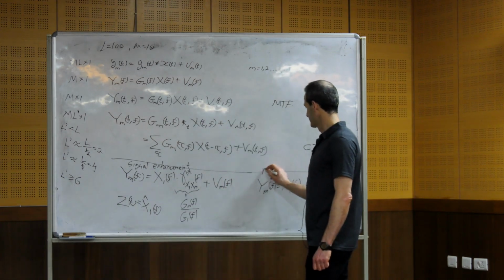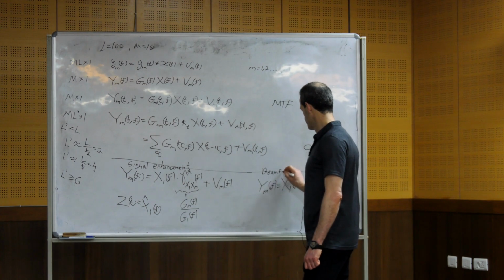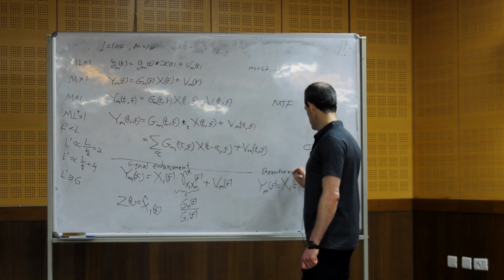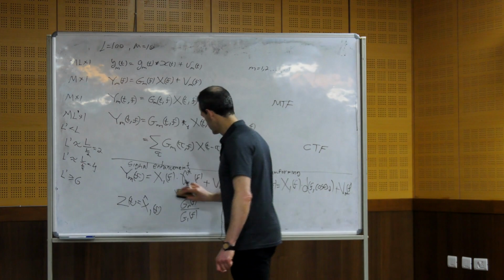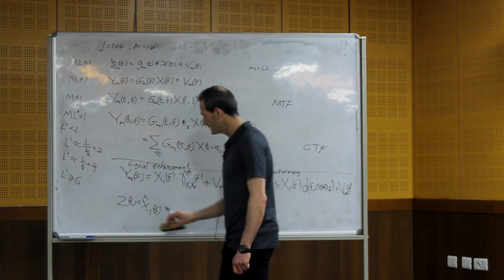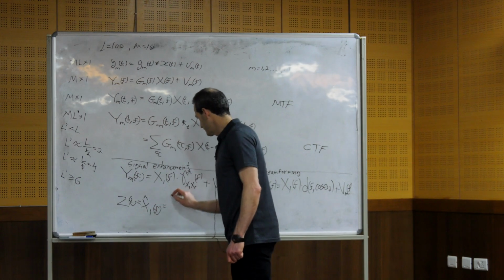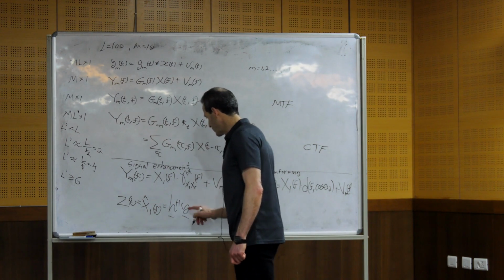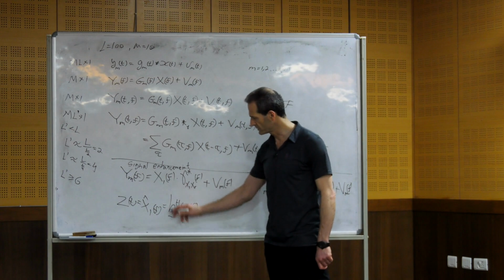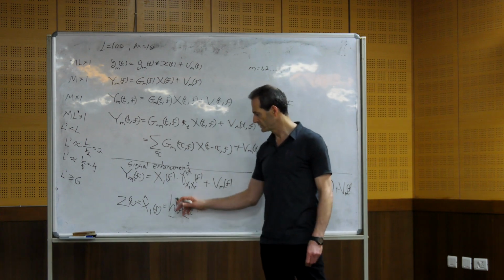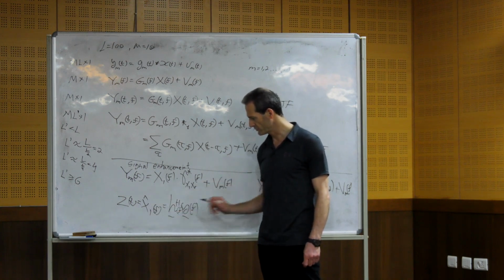And this is beamforming. Okay, signal enhancement. So we find a filter that is multiplied with the measurements for each frequency. This is called the filter that we try to estimate the desired signal, using these noisy measurements.